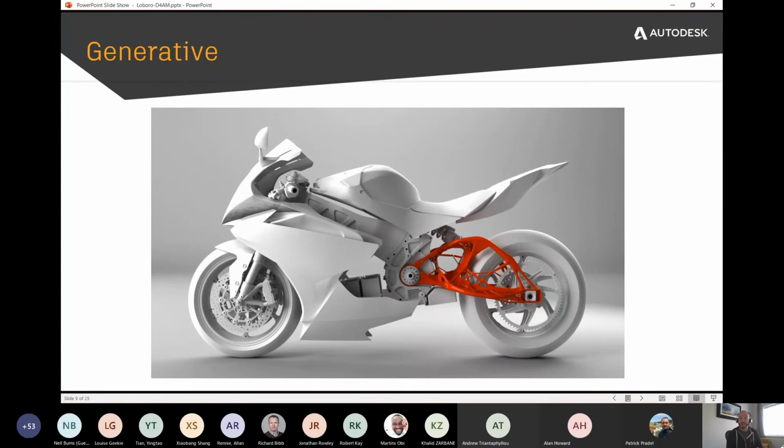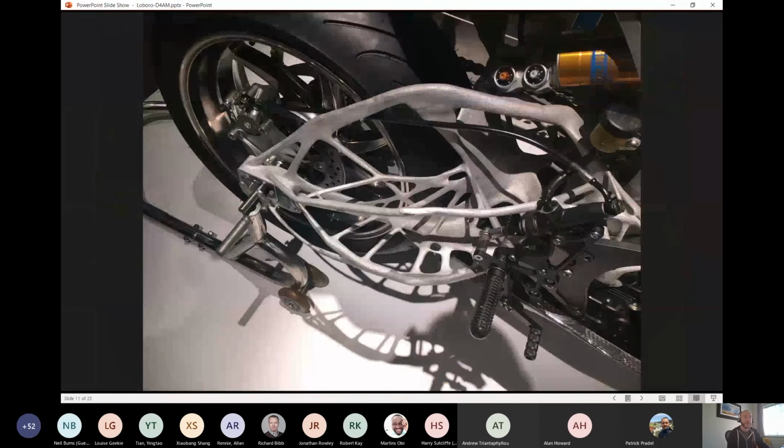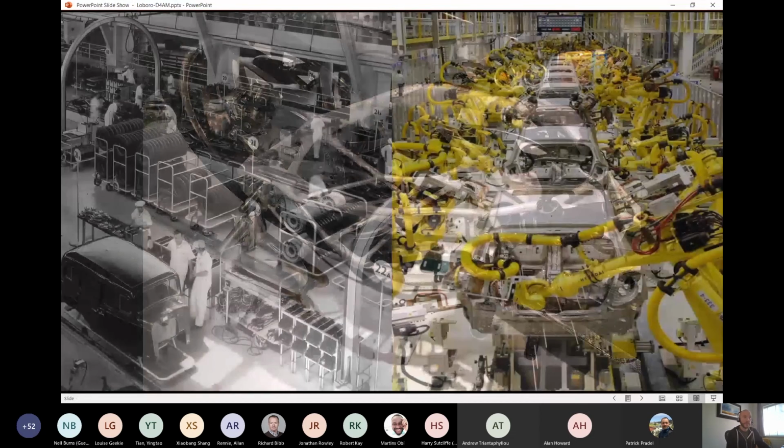Likewise, if you need a mating face, for example, you know that you're going to need a subsequent operation to actually machine or subtractively remove material from that face. So you'll probably want to add a little bit of material onto that face ready for the subsequent machining operations. You have all sorts of post-finishing operations such as wire EDM and so on. So this is the sort of finished part, and you can see it on the Lightning motorbike, and you just get an idea of some of the design considerations that went into that when it was being produced.